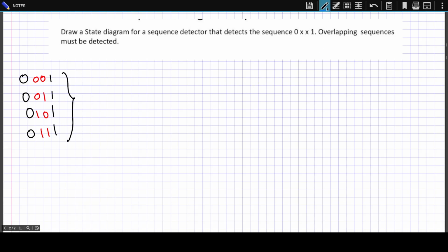Now let's start by building this. The first step is to get a reset signal and make a base state. From this state, the FSM is eagerly waiting for the input. The first number in the sequence is 0. So 0, anything, 1. If in state S0 it gets an input 0, then it will move to state S1. State S1 represents that it has matched one 0.